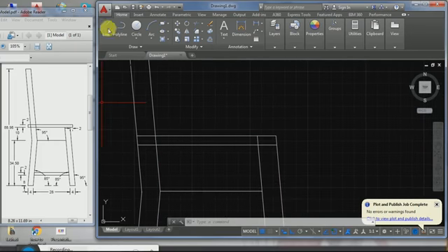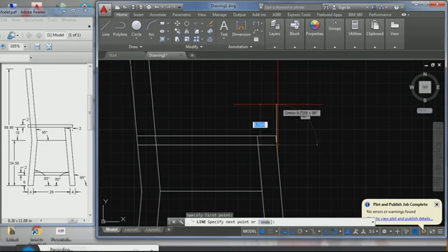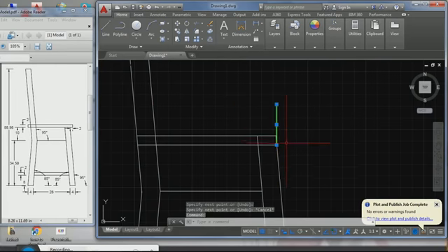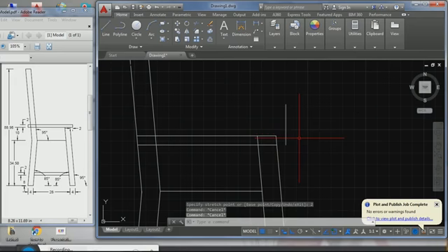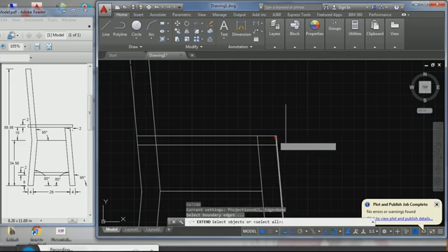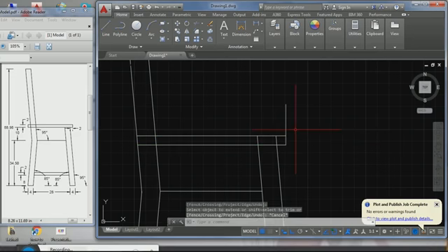In that case, the seated area is around 2 mm extendable. So create a horizontal line, then move it 2 mm, then extend. Then trim the extra.